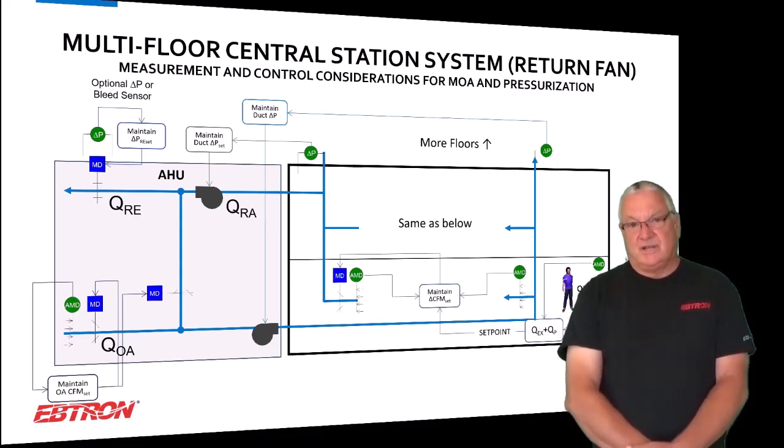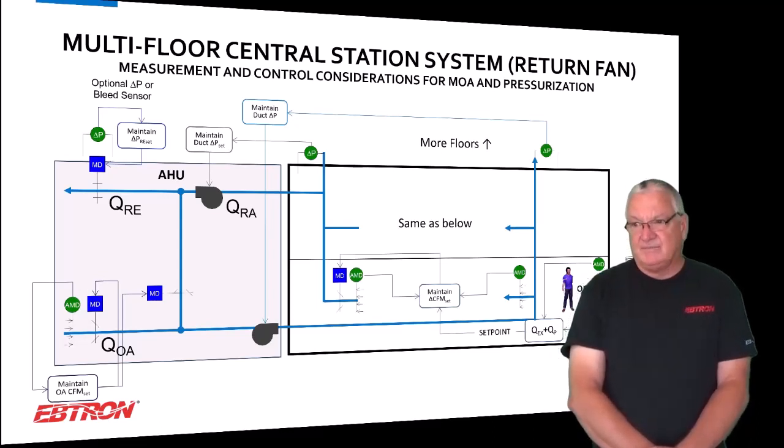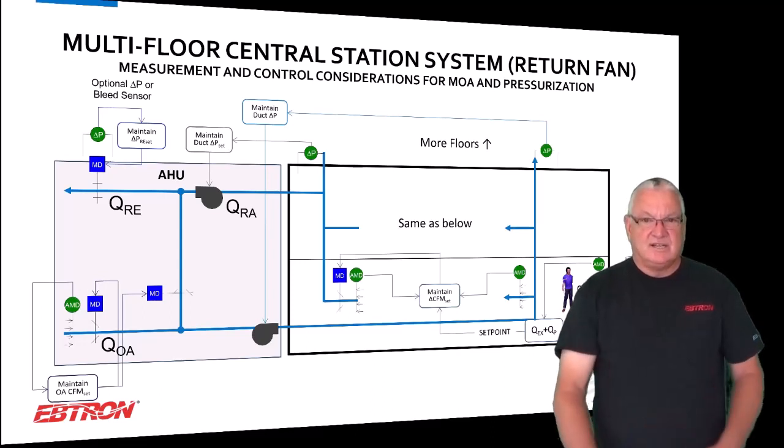If you don't do that, think about what you're doing. If you're not doing any control of the return flow, you've got, in a lot of cases, 20 floors of stack pressure that is completely uncontrolled. It's a big hole in the building. So, just things to think about.